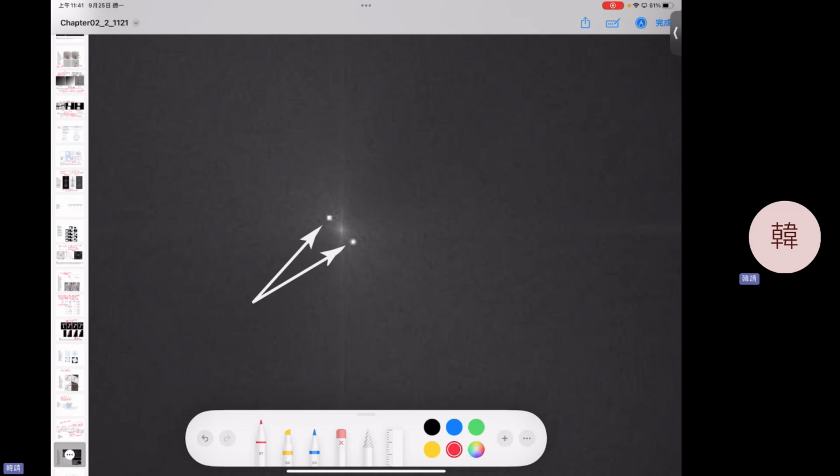Actually, there's some energy here, high frequency. Here's the center, the center is the low frequency part. Every signal, our image, has a different energy distribution in the frequency domain. The DC value is frequency equal to 0, then some low frequency band, and high frequency band. So for the different bands, distributed from 0 to high frequency, once you transform to the Fourier domain, the frequency domain, you'll see every energy component.